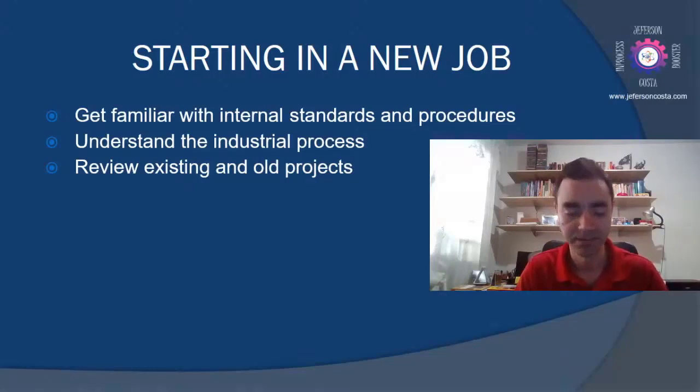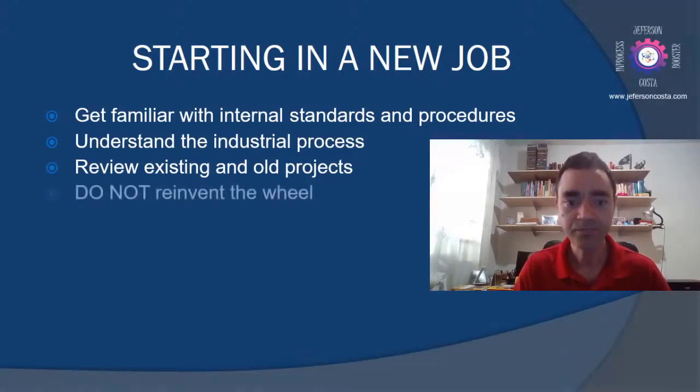For instance, if you need to isolate one piece of equipment for maintenance, many times the people from maintenance will need your support, and you say that valve B and valve A must be closed, you must make sure that those valves exist in the field.